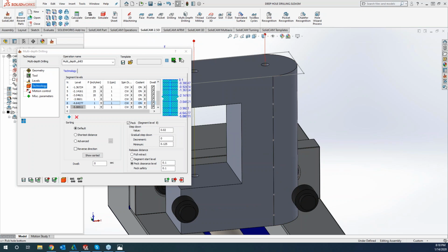I've used this in the past with very small diameter drills that are very long, where you want to keep the RPM down until it's actually engaged in the material or in a pilot hole to keep them from wobbling out of center.